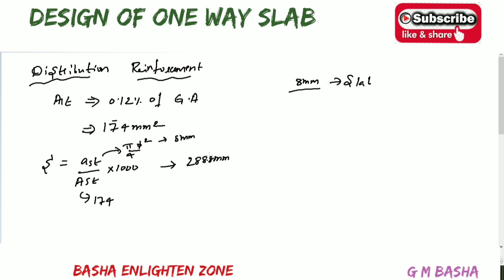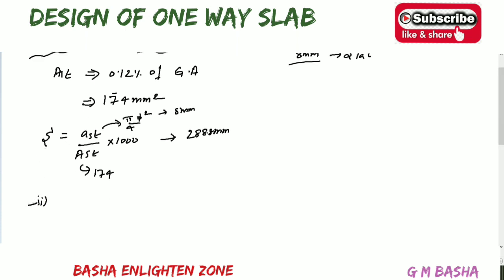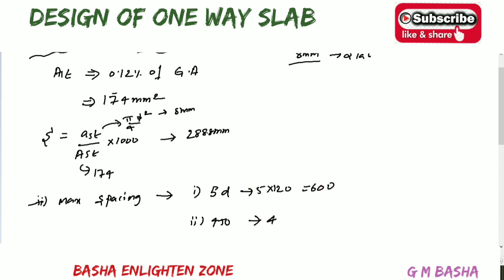mm. So again for distribution reinforcement according to our IS, same as the previous conditions, the maximum spacing allowed will be as follows. There will be two conditions. For main reinforcement it is 3 times D, here it will be 5D, and the second condition will be 450. And what about this 5D? 5 into 120, that will be equal to 600 mm, and the other value is 450 mm. So out of these three, whichever is less, we can take the lesser value.